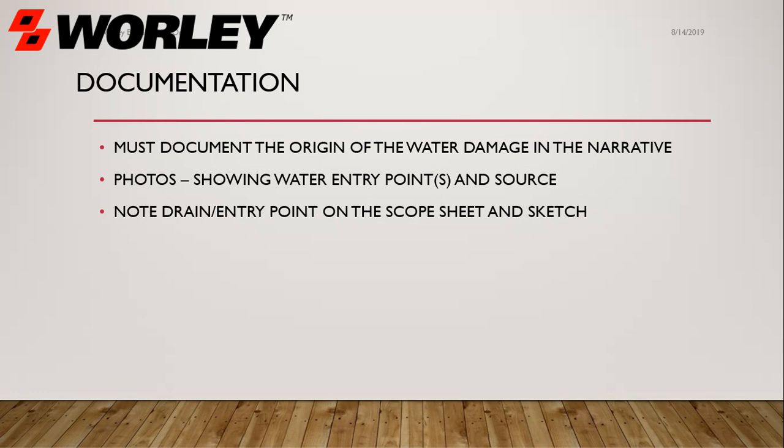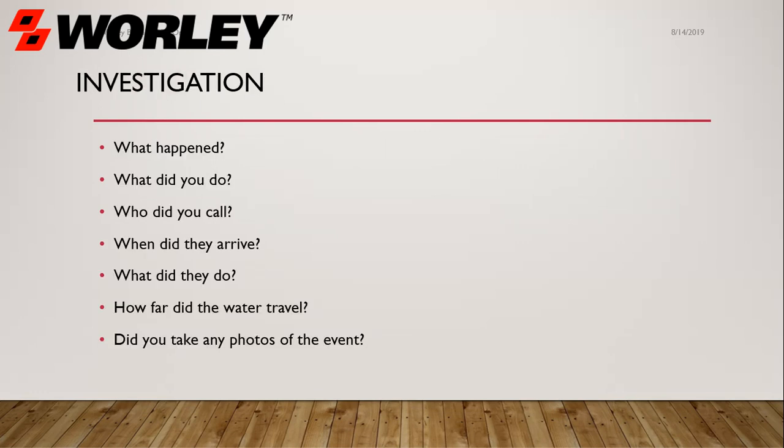And finally, the sketch piece is when you diagram, sketch your floor plan. Make sure that you're putting some type of arrows or highlighted lines in the rooms of where the water came, how far the water traveled. All of these diagrams are giving evidence of why the drying techniques were used in the particular case, or in another way, overused. So everything has to be documented, everything has to be photographed, and lay out your sketch.